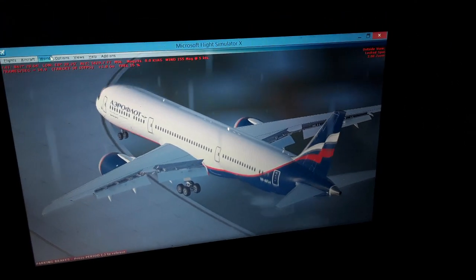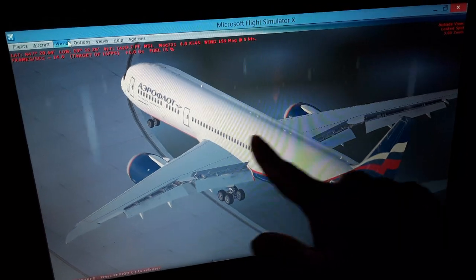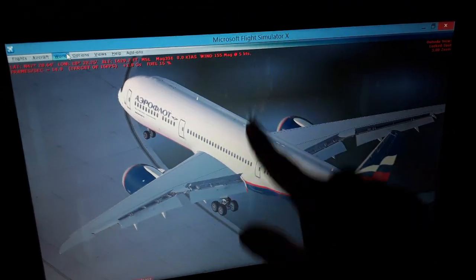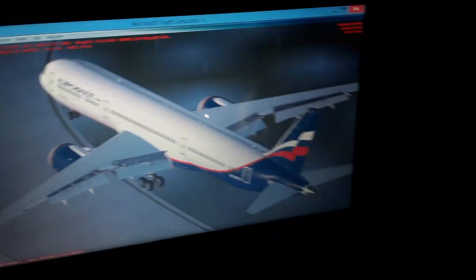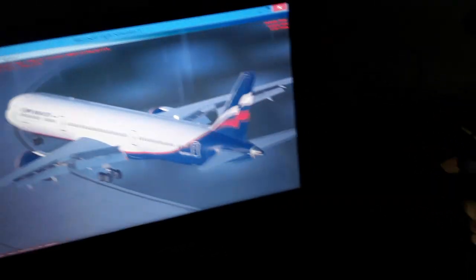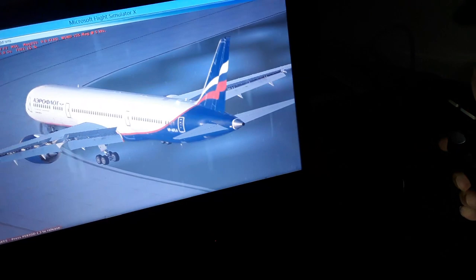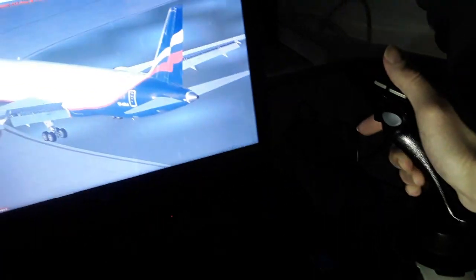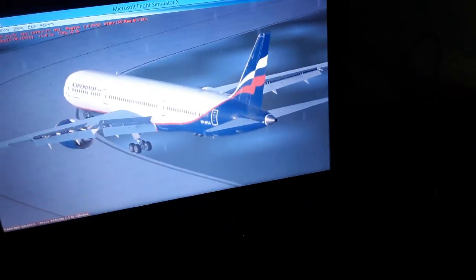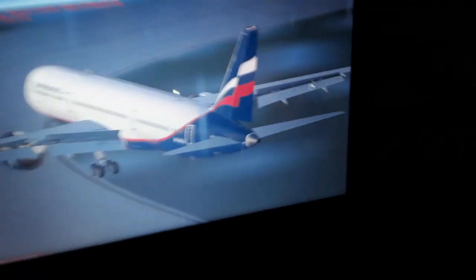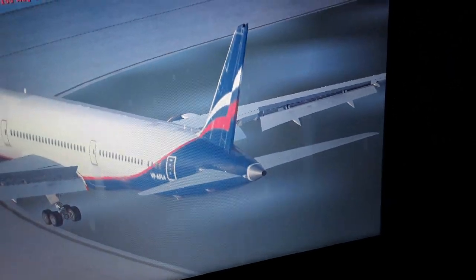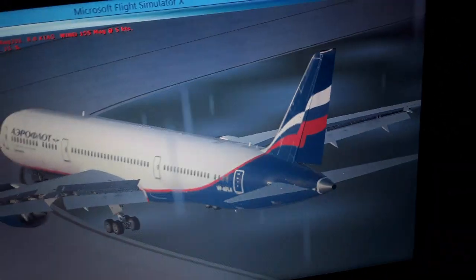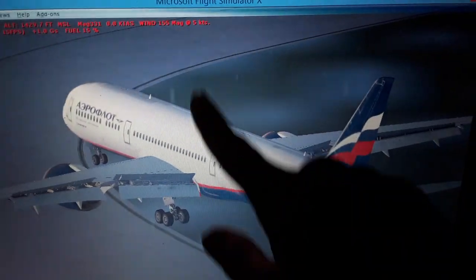So we have also here the mean aerodynamic chord. We have also the center of gravity of the aircraft. It's the yawing axis. So the yawing axis makes turns left and right over here. So left and right turns, the yawing axis. You use the rudder to make yawing turns through the center of gravity of the aircraft over here. Also to balance the aircraft flight path.